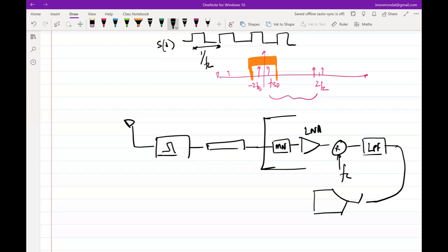if, let's say, the sampler is a part of the ADC, this is not an ADC course, so we'll just leave it to Ashwin. You have n bits. If it's an n-bit ADC, I think we all know the very famous formula of SNR equal to 6n plus 1.7 something. So depending upon how much accuracy you want in the signal that you are receiving, you build an ADC for that number of bits, right?